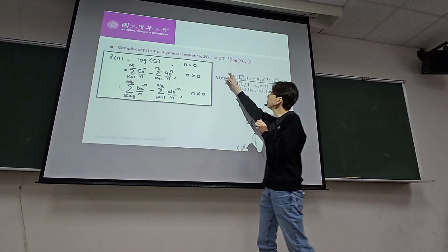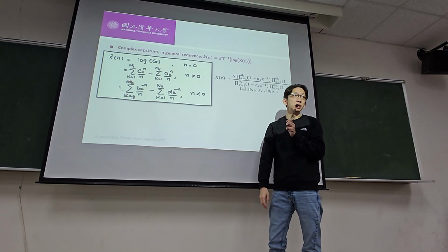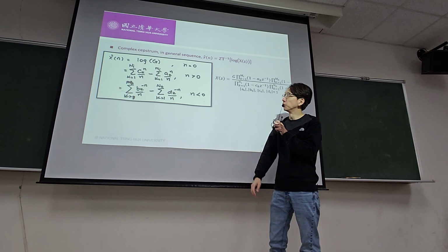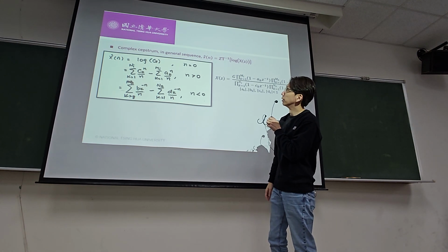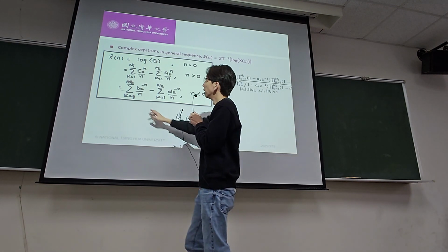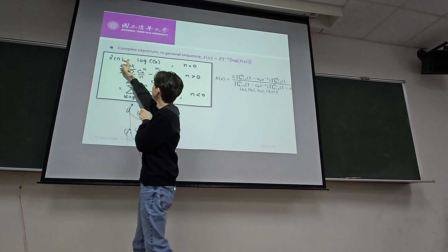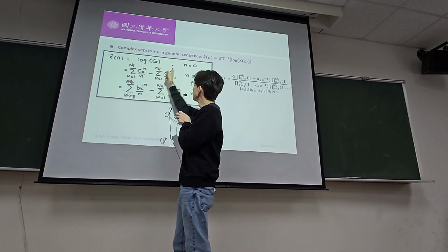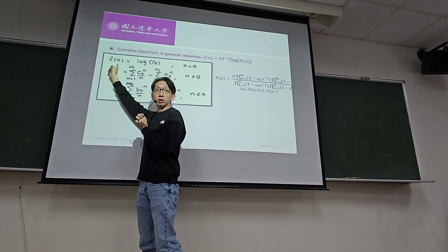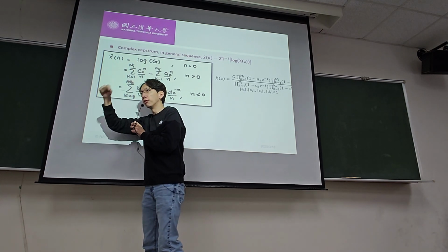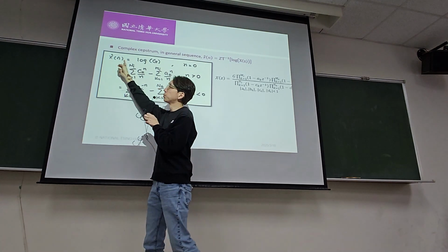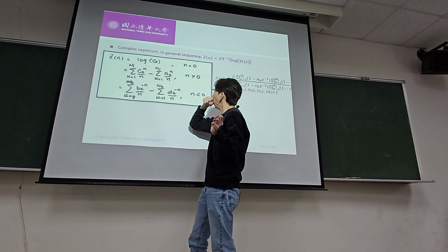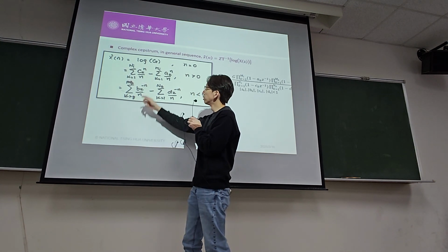So what we can write then is the cepstrum, which is the inverse transform, because we work in the Z transform, of the log of the transform. If we write them in this particular manner, then we can actually write out three different parts. x hat of n equals log of g at this particular n index, the cepstrum, the quefrency index. So x prime of n plus log of g when n goes to 0. When n is greater than 0, you have